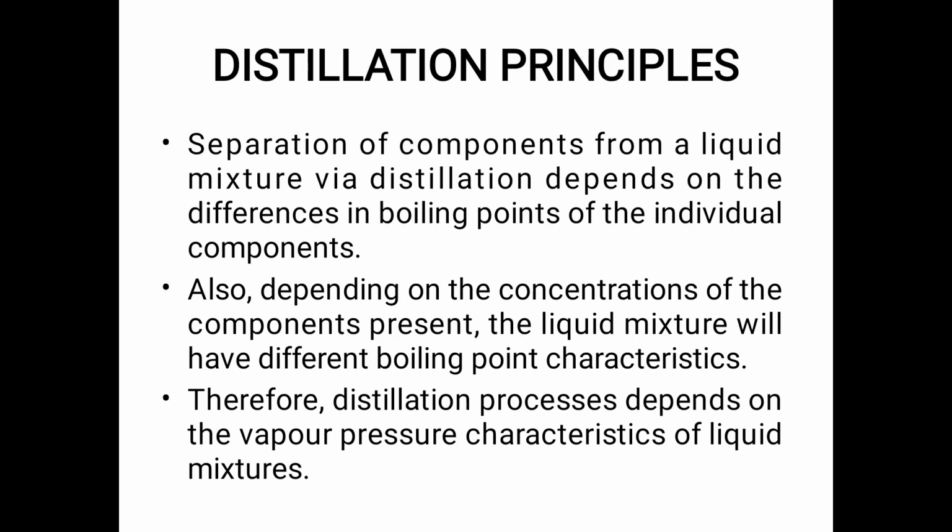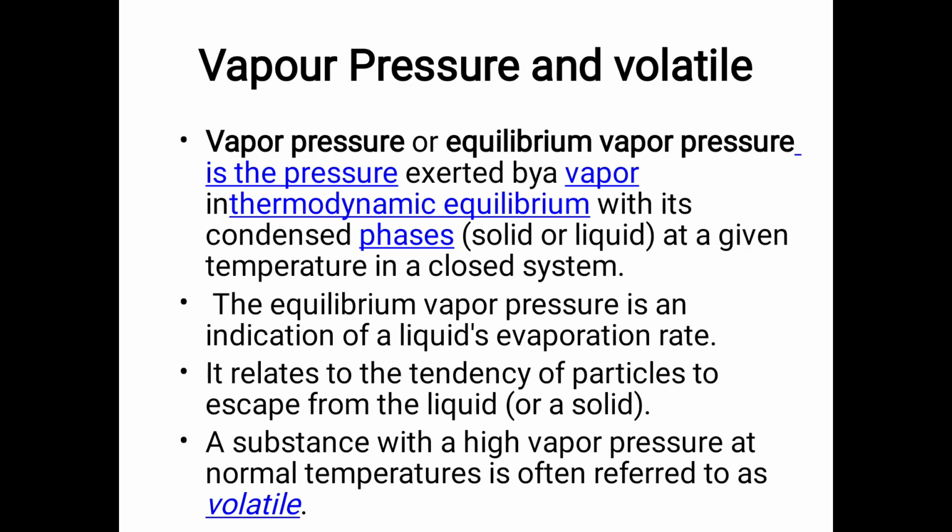Distillation principles: the separation of components from a liquid mixture via distillation depends on the difference in boiling points of the individual components. Based on the boiling points, the components are separated. Also, the concentration of components present in the liquid mixture gives different boiling point characteristics. Therefore, the distillation process depends on the vapor pressure characteristics of liquid mixtures. What is vapor pressure and what is volatility?